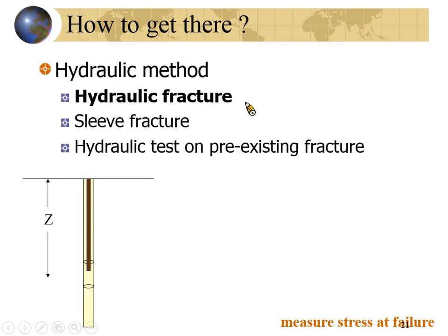I will start from the hydraulic fracture method. So this method needs a borehole. If we want to measure the stress at a great depth, like 1 kilometer, you can drill a borehole to the depth where you want to measure the stress.